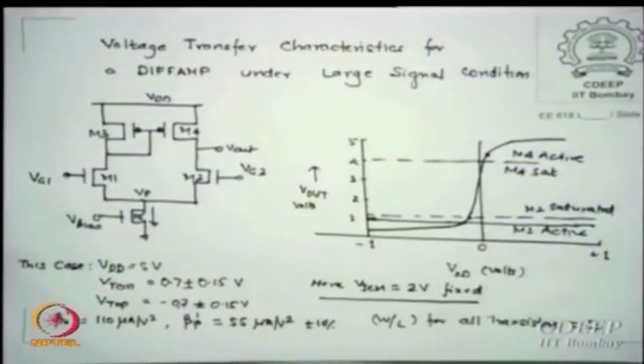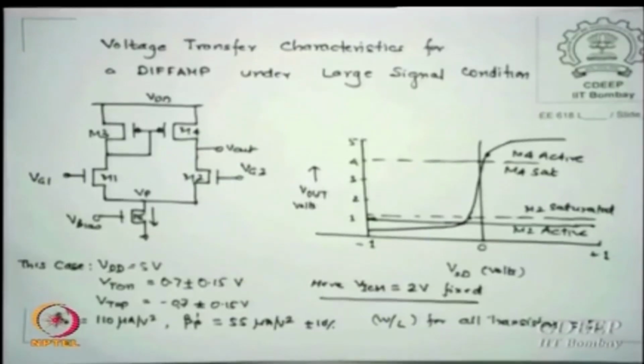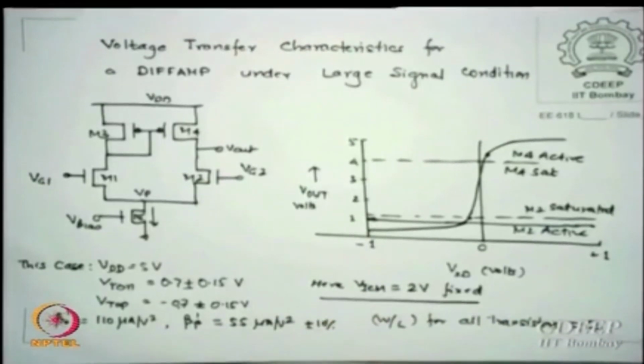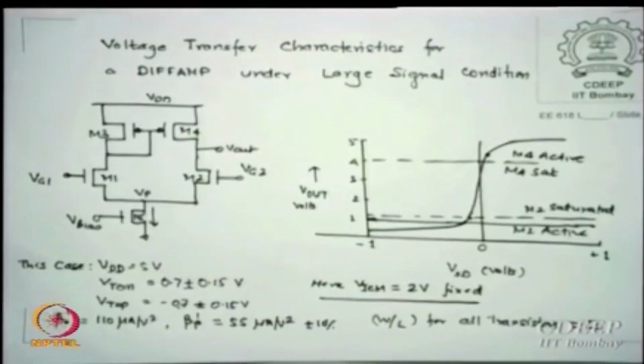Okay, there is another number which we are going to use, called input common mode voltage, which is defined as VICM, and typically for this supply, we will come back to this VI, this is one of the things which we want to calculate or evaluate, but right now assume it for this is roughly 2 volts which is fixed. W by L for all transistors chosen here are 2, no reason, just that. So if I use this,